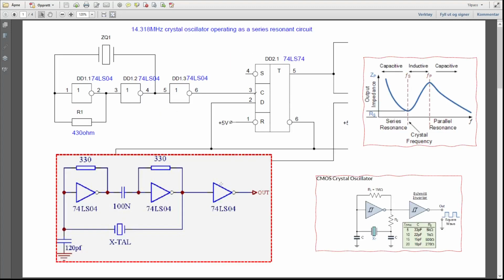Whereas this circuit here, even though it's a logic gate, acts as a follower, because there is a linear function between the input and the output, and it's only in our minds that we have set the boundaries for high and low on this kind of circuit, whereas the Schmitt trigger does not allow the output to stay in an undefined state. So this kind of oscillator has an advantage over the TTL gate kind of oscillator.